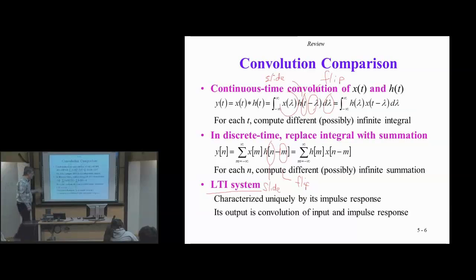So we've characterized an LTI system uniquely by the impulse response. So if you know the impulse response, and I give you an input signal, you can always compute the output in the time domain by convolving the impulse response and the input. And this is what filters do in the time domain. They do convolution. They implement convolution. I don't have to tell you any more than that. Just the impulse response.